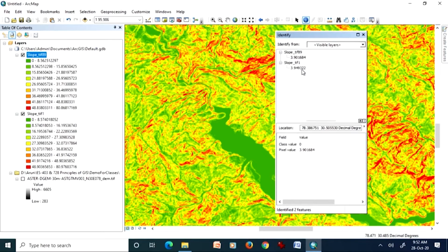and when jet factor is 0.5 times 0.89, then it is 3.90. So again, what we are observing is that if we keep jet factor 1 by mistake, when our x, y and z units are not the same, then it is going to overestimate our slope values. So it is always desirable that we take care of these x, y and z scales, that they should be equal.